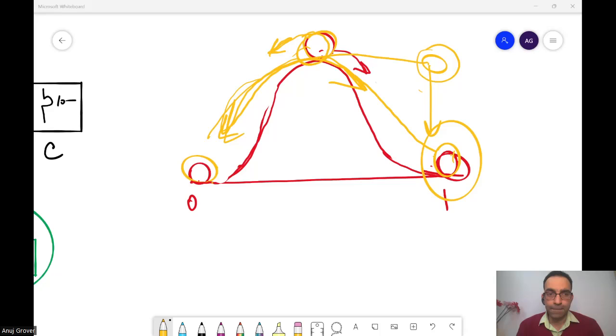Okay, so we can put the sense amplifier at different voltages and the array at different voltages, and because I am able to keep the sense amplifier at different voltages, I prefer to keep it at a Q point to make the sensing faster. I can. And that is what we did, and we saw some benefits. Okay, fine.